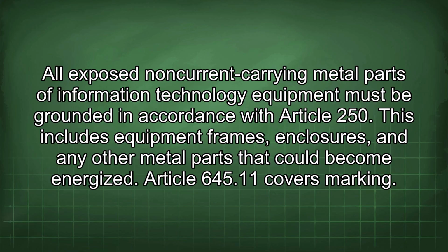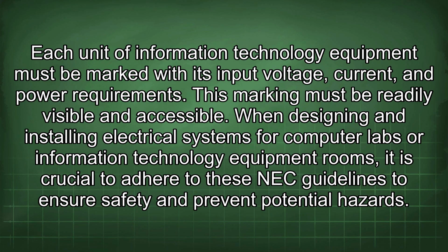Article 645.11 covers marking. Each unit of information technology equipment must be marked with its input voltage, current, and power requirements. This marking must be readily visible and accessible.